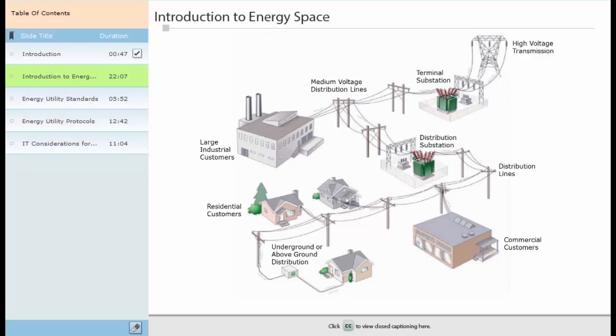The power generation station generates high voltage electricity that can be transmitted over very long distances. As electricity flows through the grid, it reaches a transmission station, where voltage is stepped down using transformers. Distribution substations reduce the voltage further in order to supply power to homes and businesses. Distribution substations consist of primary and secondary substations, which can be found underground, above ground, or suspended from a utility pole. European grids have secondary substations. Electricity reaches the end of the electricity grid when it enters the customer's meter. Most often, the meter is owned by the utility company and is considered to be part of the grid.